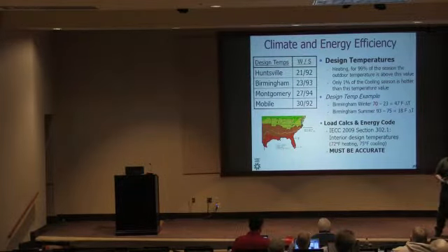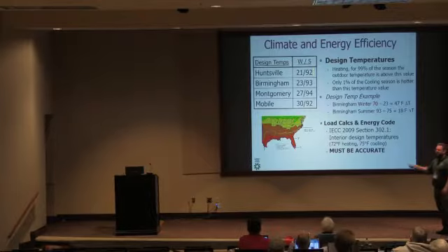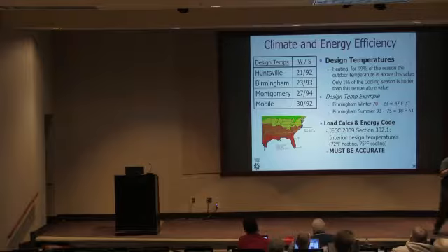So if you have the chance to look at load calcs, you can look at design temps, because these are basically set by ASHRAE, and you can see whether they've used correct design temperatures. It's one of the first and easiest things to fudge if you're trying to manipulate the load calculation.